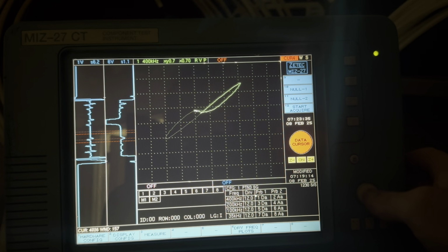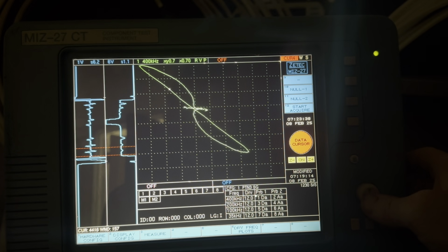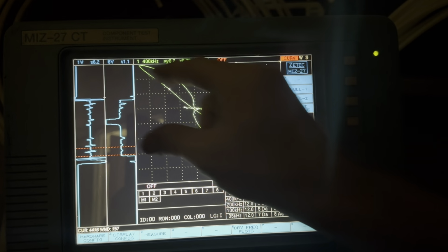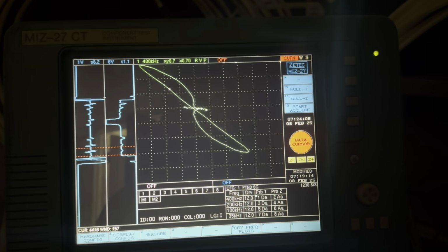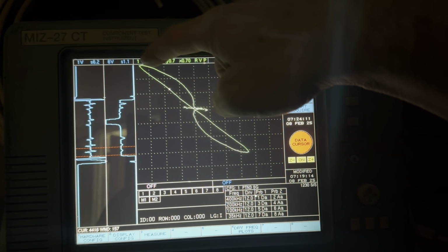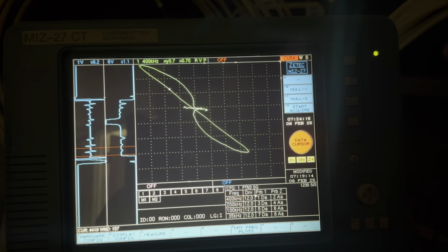So what we do is we calibrate our 100% hole signal, which is right here. We set it to 40 degrees because of what they figured out in the early days. Clyde Denton from Z-Tech had a lot to do with this. They could set it at 90 degrees, they could set it at 140, they could set it to 0, or if they set it to 40 degrees, what they figured out early was that ID flaws, which you probably saw fewer of back in the days, would land between 0 degrees and 40 degrees, or a fairly small phase window. And OD flaws, which you probably saw more of, would occur from 40 degrees all the way over to about 180 degrees. Now notice the reference point for zero is flip-flopped from your normal studies in math and science.